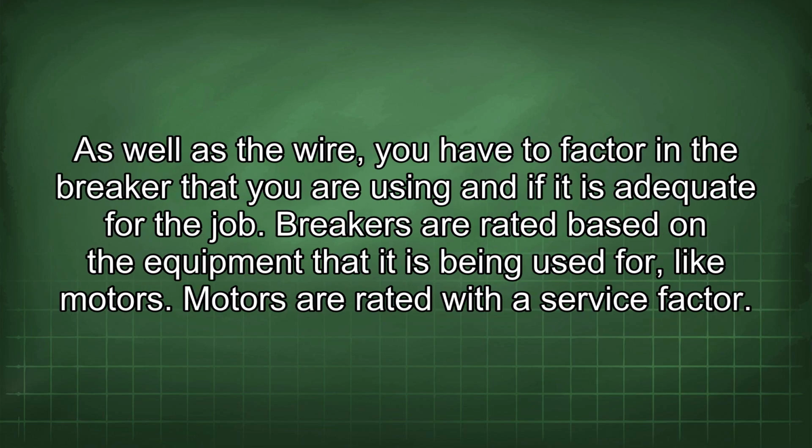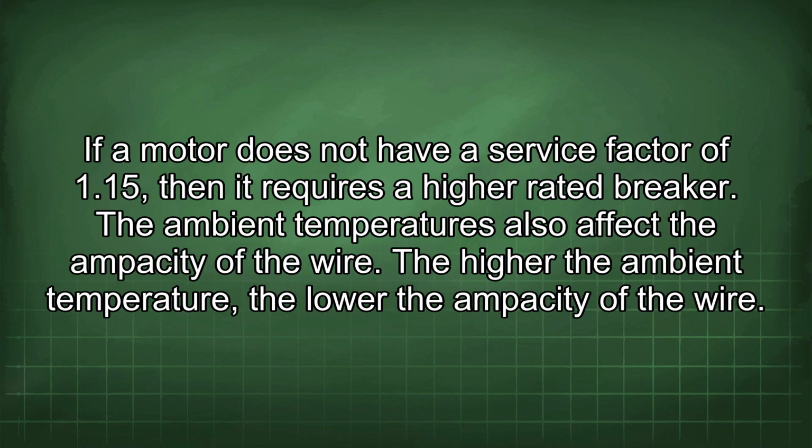As well as the wire, you have to factor in the breaker that you are using and if it is adequate for the job. Breakers are rated based on the equipment that it is being used for, like motors. Motors are rated with a service factor. If a motor does not have a service factor of 1.15, then it requires a higher rated breaker.